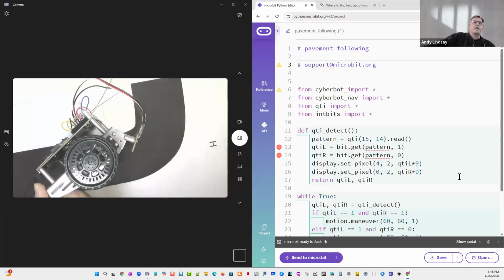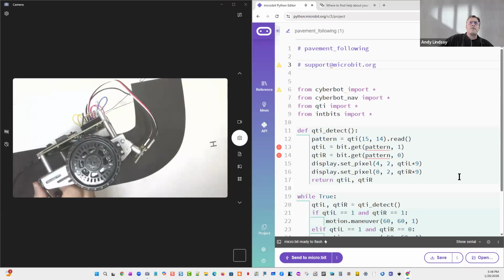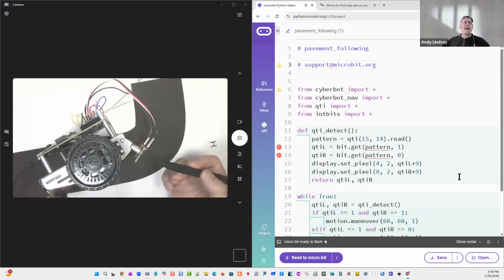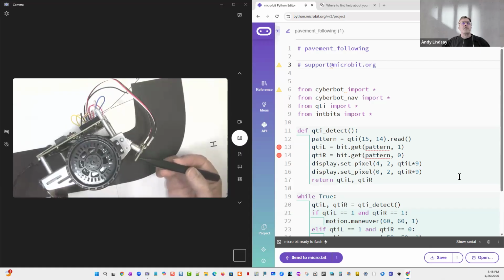And like I said, go ahead and see if you can adjust the distance. I would avoid initially getting closer than 3/8 of an inch between this sensor, it's right about there, and the surface of the paper.